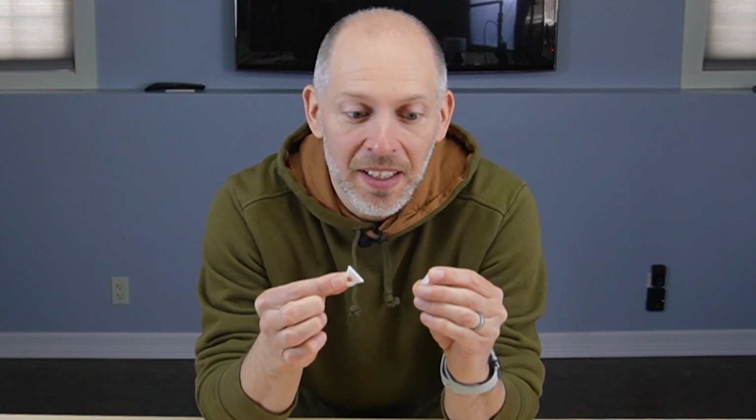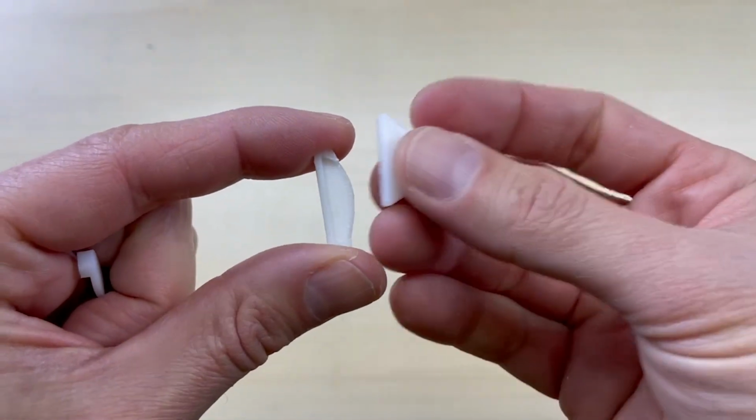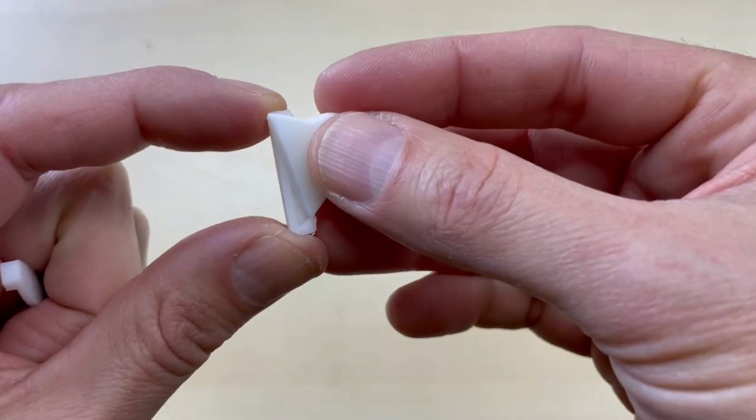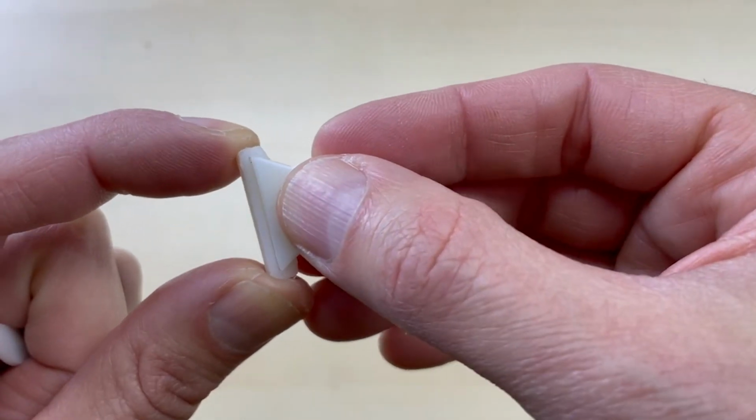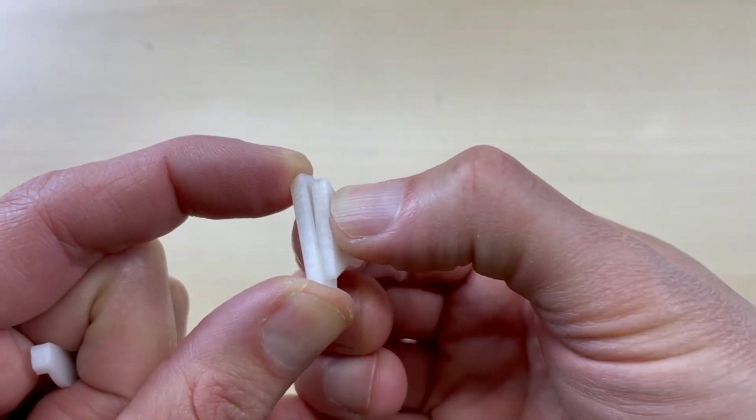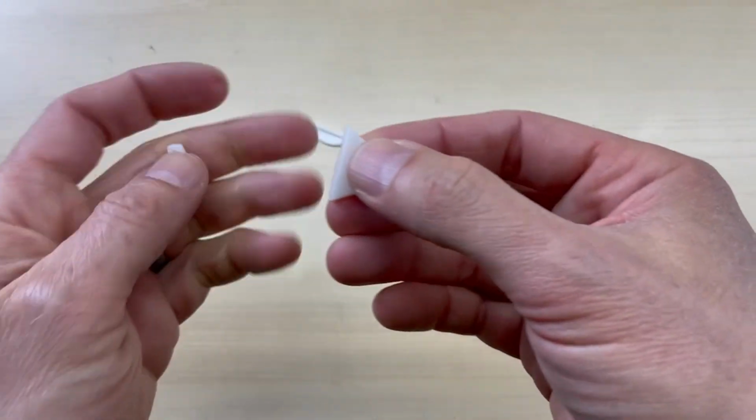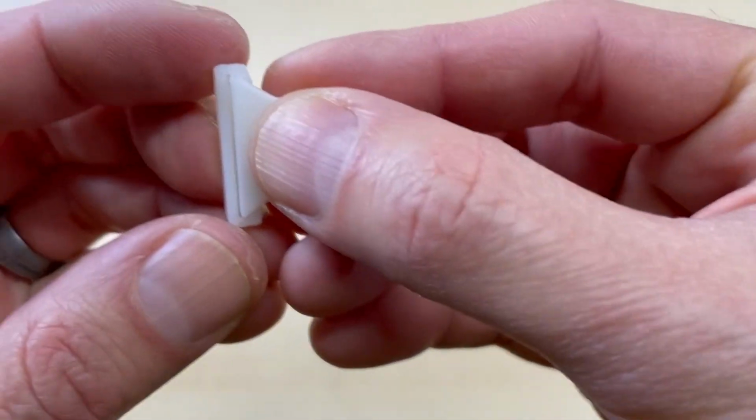When I print parts like this, I always add small offsets, and I do a bunch of prototype prints before I commit to the full job. I just temporarily cut away the majority of the design so I can print the parts that interface with each other. For this print, I found that a 10 thou or 0.01 inch gap will compensate for machine tolerances and material shrinkage.